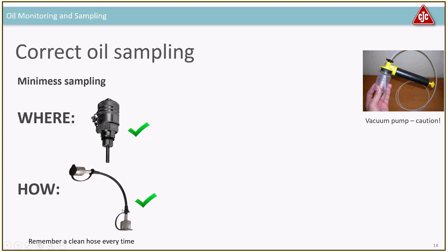If you're using vacuum pumps and these coiled up hoses, again, please be aware that the coiled up hose is really difficult to straighten and get in the right position you want. So you want to actually, with tie wraps or something, strap it onto a rod or something so you know exactly where you put it in the gearbox. Otherwise it's very difficult to know where it's going, and maybe it's actually getting in between the teeth and the plastic will be eaten up by the gear teeth, or you'll be scraping down the varnish from the sides and so on. So please be careful with vacuum pumps.